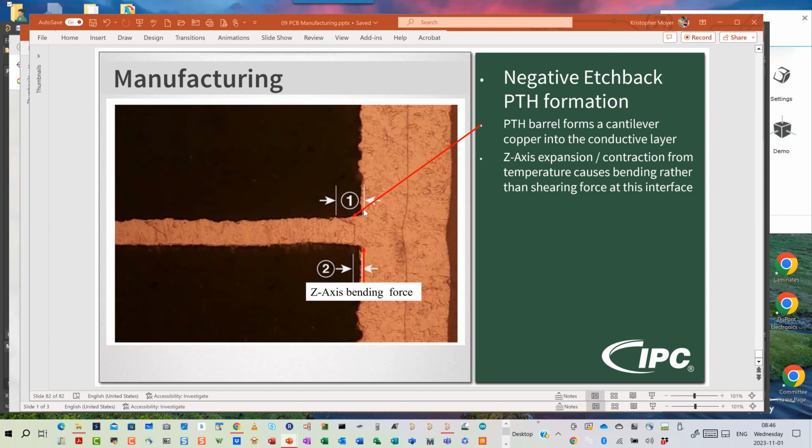And this would be on every barrel, every plated through hole? Yep. Every layer that is attached to an inner layer. So, for example, typically what we're going to do, and I didn't talk about it in this slide, I talked about it in my military and my RF lectures for those reasons. Oftentimes, the fabricators ask to do what's called remove non-functional inner layer lands. So you would actually only have this where you make a connection, because if you have the normal donut ring that would be around your plated through hole barrel, if there's nothing connected to it, the fabricators just want to remove it because it causes other problems.